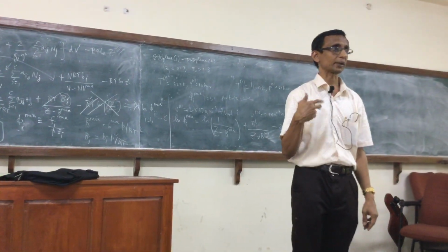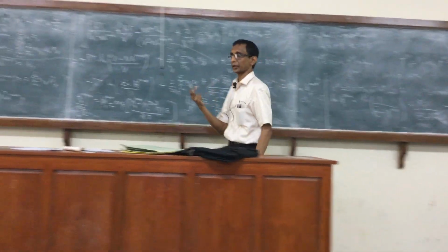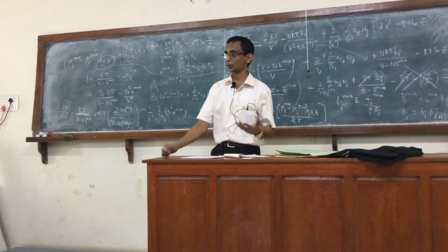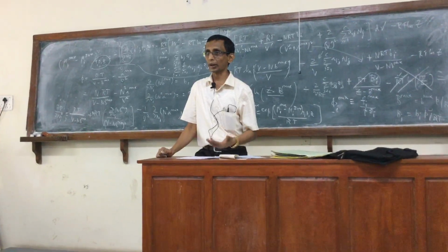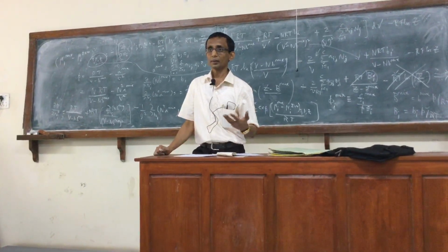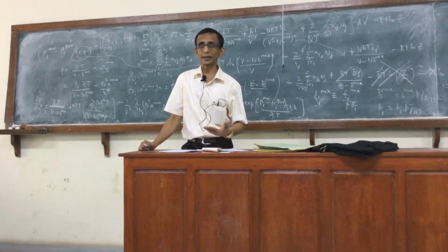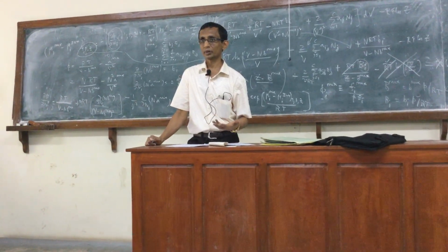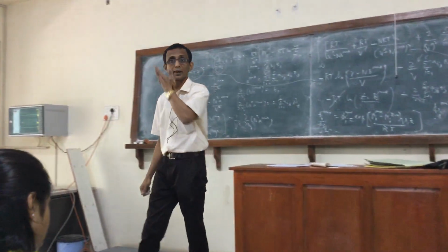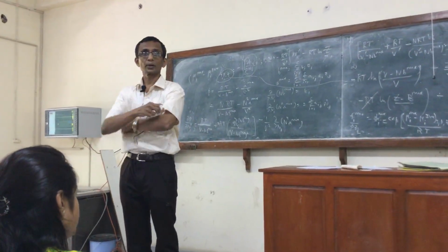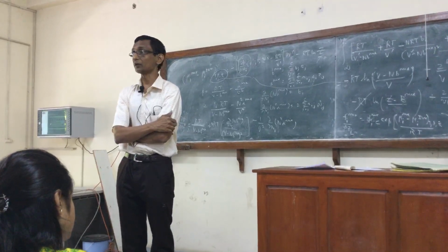By calculating the fugacity coefficients and comparing them to 1 for the 2 components, you can get some more idea how close the behavior of the actual mixture is to the ideal gas mixture. So that is what I have to say. Are there any questions on the calculation of fugacity coefficient from an equation of state?